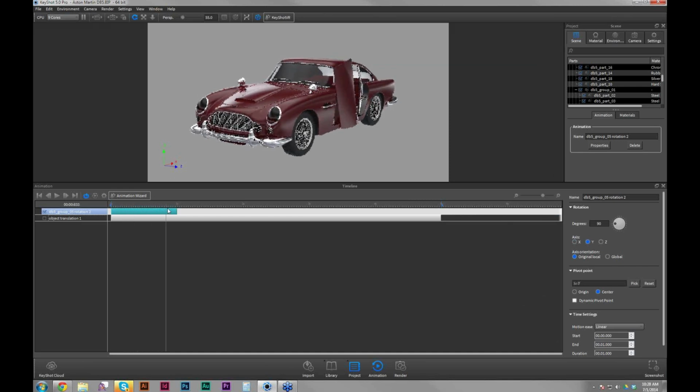Nope, it's not the right axis. And click on Z, and yeah, that's kind of the right axis, but not quite the right pivot point. You might be noticing that while I click Z here on the coordinate legend, it's actually rotating on the Y global. That's just where I said previously how the axis orientation is more apparent probably with rotations. Here you can see that. So what's going on here is it's actually rotating on the original local.